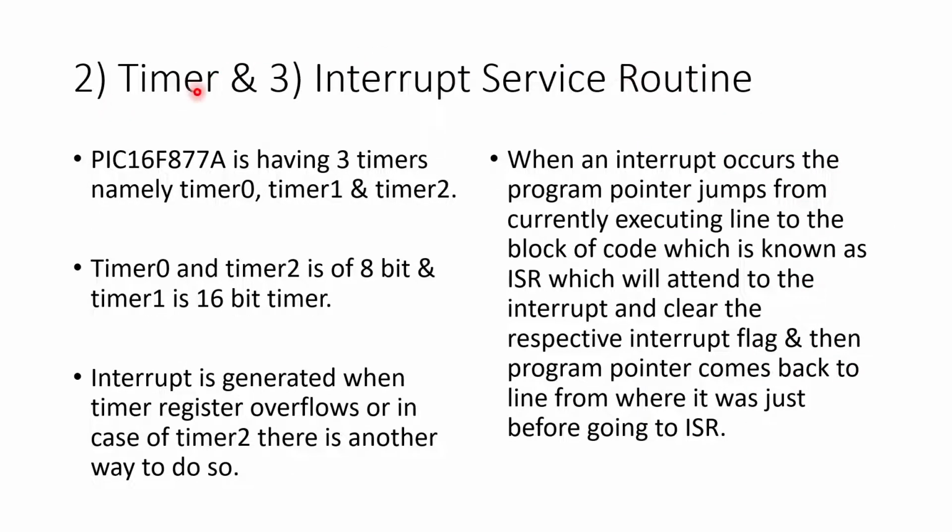Now let's see timer. PIC 16F877A has 3 timers, namely timer 0, timer 1 and timer 2. Timer 0 and timer 2 are 8-bit and timer 1 is a 16-bit timer. We have used timer 2, and I will mention why we have used timer 2 and not timer 0 and timer 1.